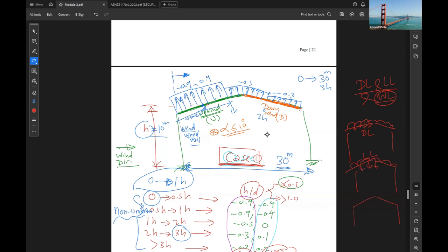And you have upward pressure from wind load. So when you sum this together, the resultant might be downward or upward, right? Yep. So some loads are downward, some loads upward. So this might be upward or downward based on the values.